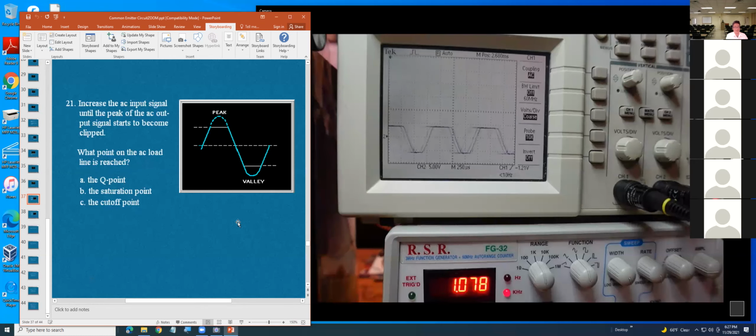Okay, when they see the signal, they cut it either on the top or on the bottom. That means they will be saturated or they will be cut off, then no more amplifier. Okay. That means in the amplifier, you can use the formula IC equals beta times IB. However, if they saturate, you cannot use this formula.